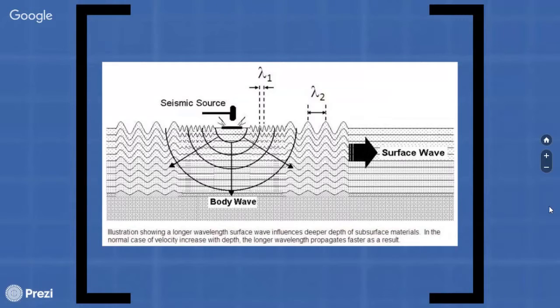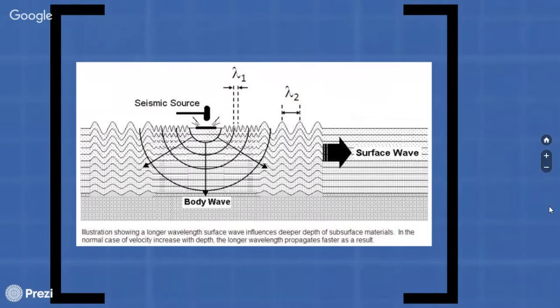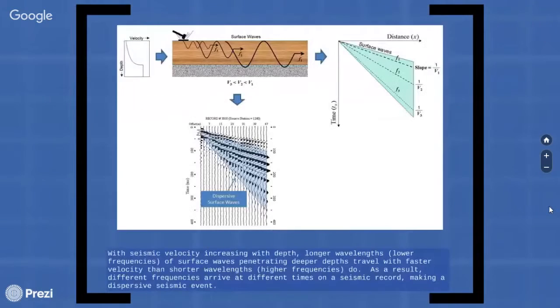Meaning different frequencies have different propagation velocities. Two types of surface waves are generally known: Rayleigh and Love waves. The disturbance vibration direction of the former is perpendicular to the surface, whereas it is parallel for the latter.